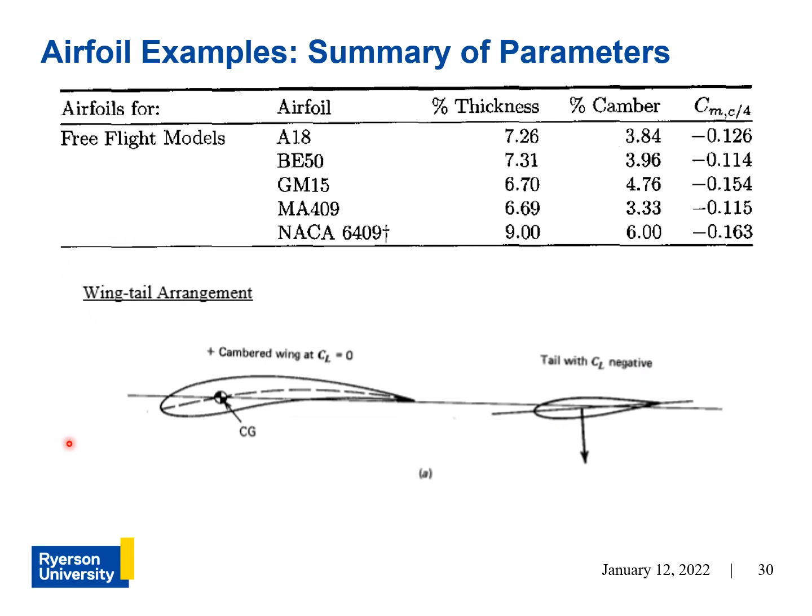And again, here is a picture of a wing-tail arrangement. And here is the wing body, and it will have a tendency to pitch downward. You will have to use a tail at a negative incidence angle, and here you can see a negative incidence angle just means it is below this line here, and that will cause the angle of attack to be negative and have a negative lift.